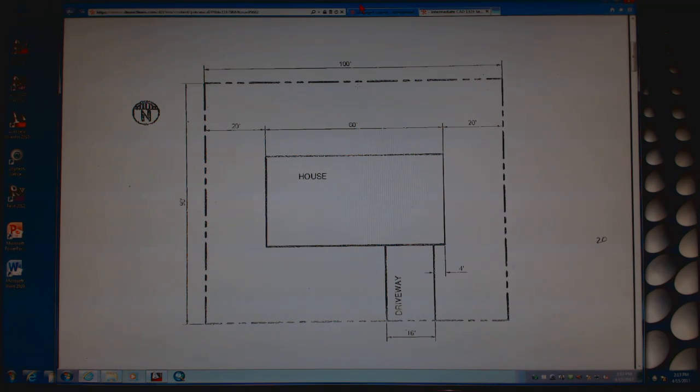100 feet, you need anything that has feet and inches to be 100 foot dash 0 inches, or 20 foot dash 0 inches. You may want to make a note of that. If it's strictly inches with no feet, it just needs to say inches. So it just needs 6 inches, 3 inches. But if it's foot, it needs to be foot dash 0 inches. That is strictly one little setup under primary units inside dimension style. Okay?